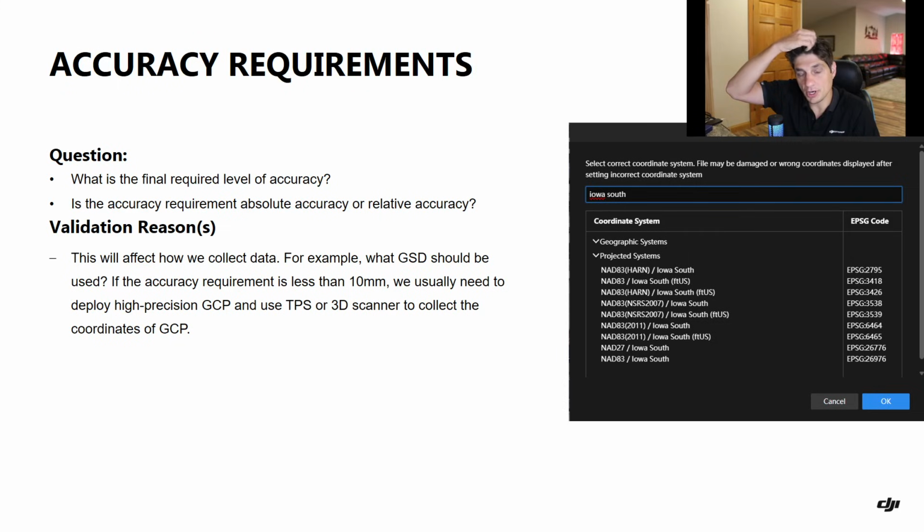Generally, when we are capturing data and making a good 3D model, we're having high levels of relative accuracy, but that doesn't necessarily mean that where it's being placed on the Earth is going to be accurate. With relative accuracy, you could actually be off when it comes to scale, but that just means if I measure on one part of the 3D model, and I measure on another part of the 3D model, if they are the same distances, do they show to be the exact same length on those two different segments on the 3D model? Do you have any warping going on within that 3D model on one side of the asset compared to the other? So really understanding what levels of relative accuracy you need, as well as how accurate this needs to be to the real world Earth.